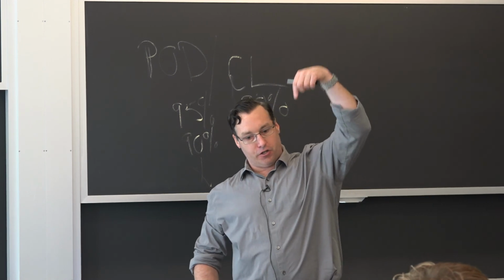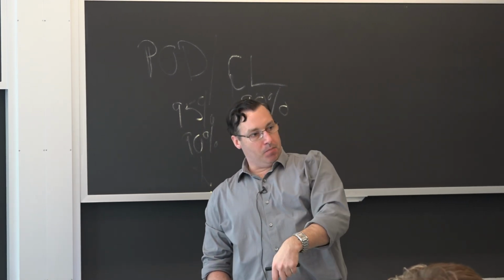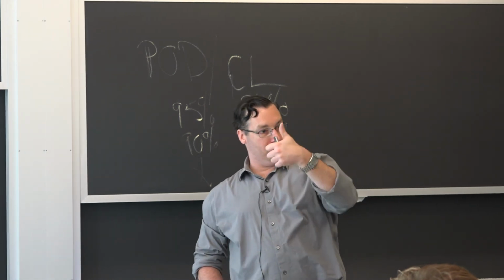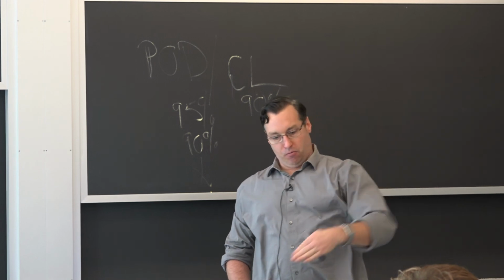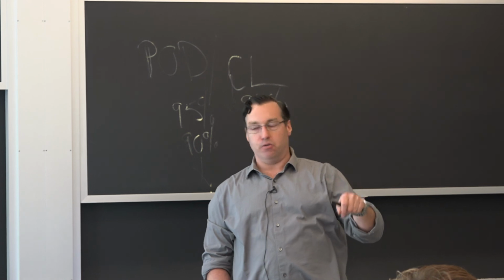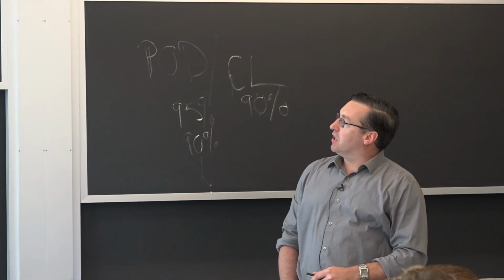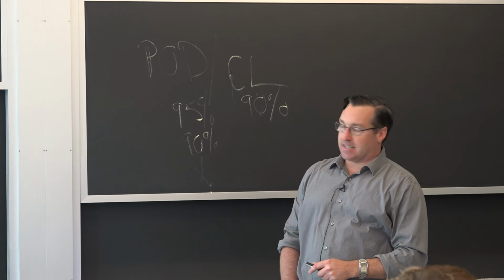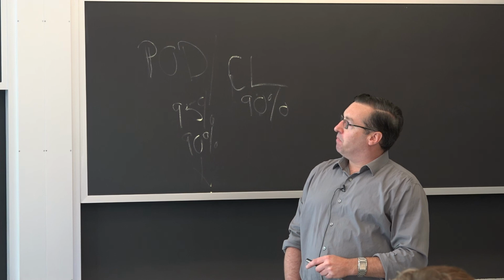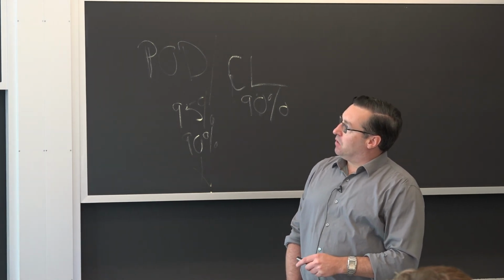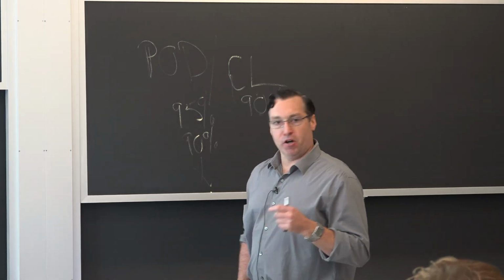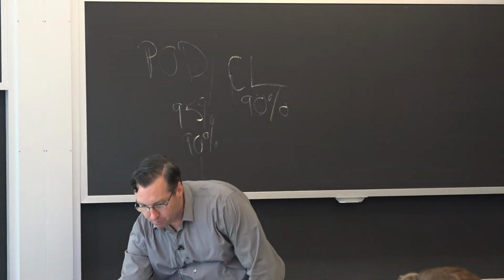It's not a longitudinal where it's pulse echo, where it's shooting straight down and it's just a pulse, it hits the back wall and comes back. This actually is going through and it's steering through the component at some specified angle based on your transducer. But what that allows you to do, being able to pulse the beam, is now you can size. You have much more capability to size the flaws. And this right here would be 1/64th of an inch. So we're getting down to pretty small flaw sizes that you can find.